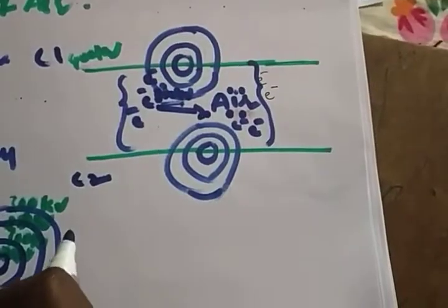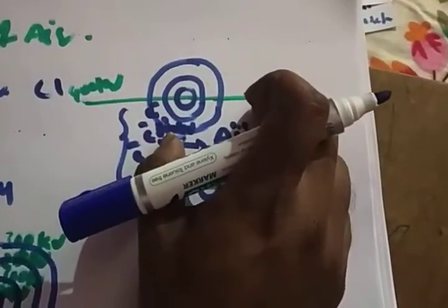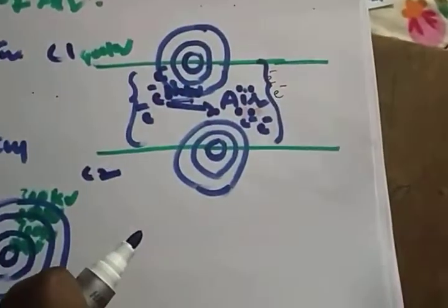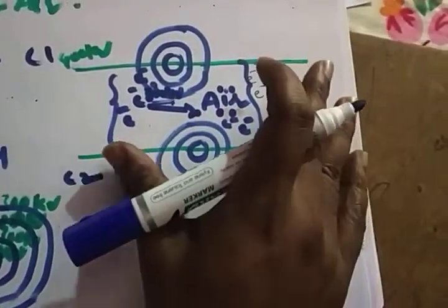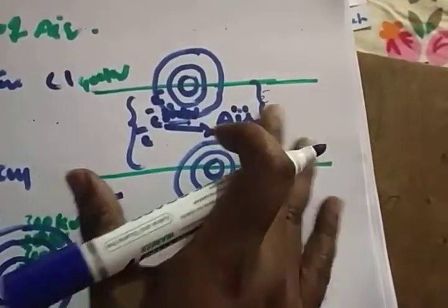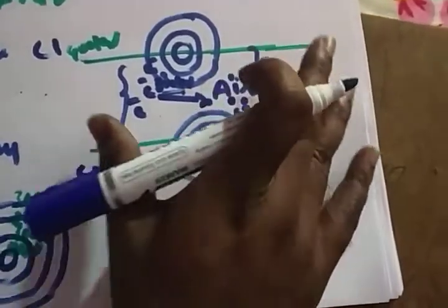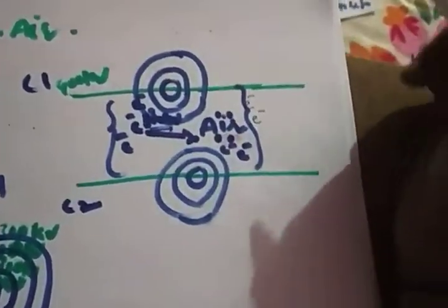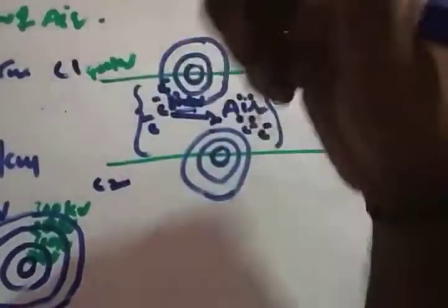So there the air got some breakdown. It will act as a conductor here. Then there will be some hissing noise and some violet glow developed. That hissing noise and violet glow also develop ozone gas. So we can call it a corona. I hope it's clear. That concept, the forming of hissing noise and violet glow, we can call a corona.